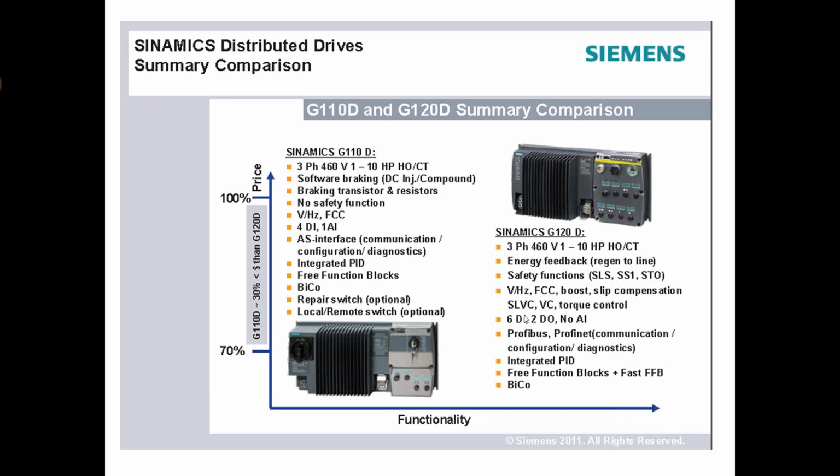You can see that there's a little bit more I/O on the G120, and it has the full communications of Profibus, Profinet available to it. The G110 is ASI interface, so it's very limited in the communication scheme, but still a very good local drive.